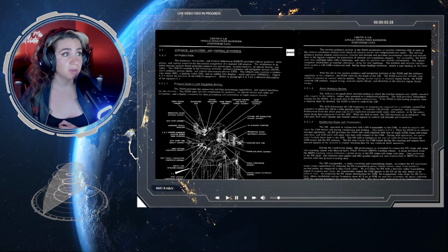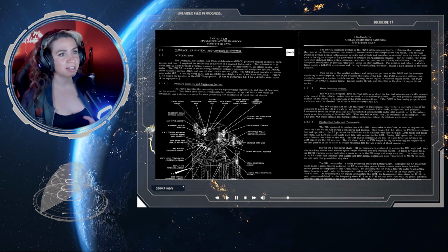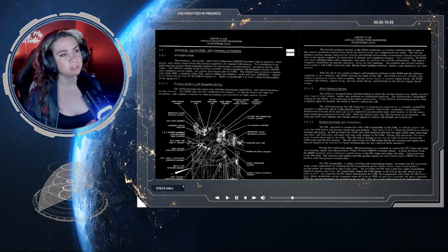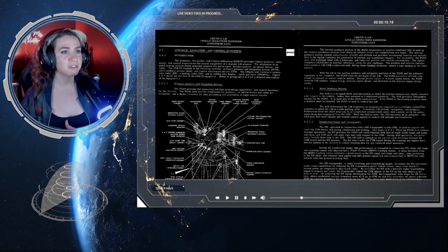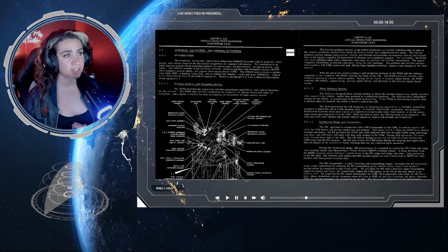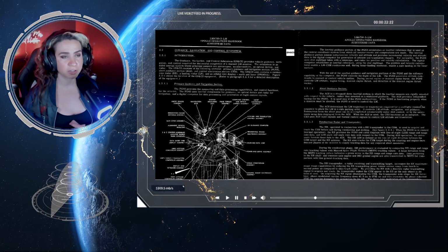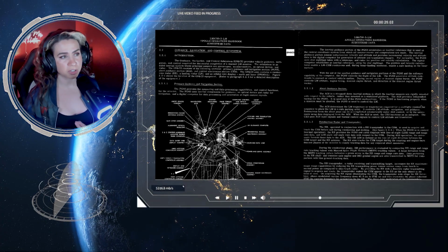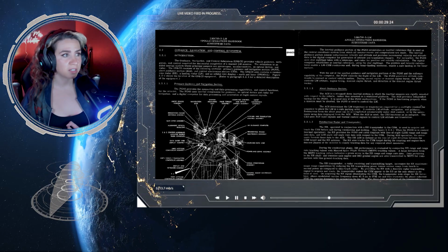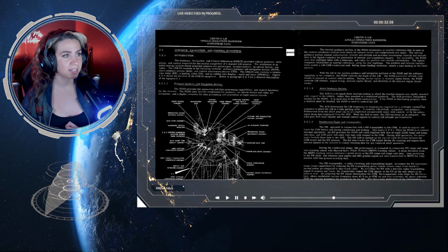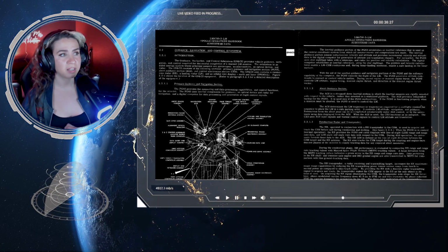Alright, so the inertial guidance portion senses instantaneous velocity and attitude and provides incremental velocity and attitude data to the digital computer for generation of attitude and translation changes. For navigation, the PGNS uses star sightings taken with a telescope and radar for position and velocity calculations. The digital computer establishes an inertial reference using the star sightings. The position and velocity calculations enable the LM-CSM rendezvous and during lunar landing missions enable a safe landing on the lunar surface.